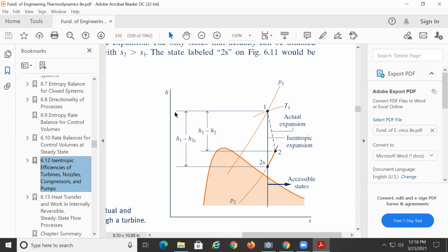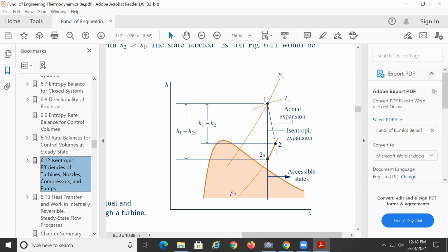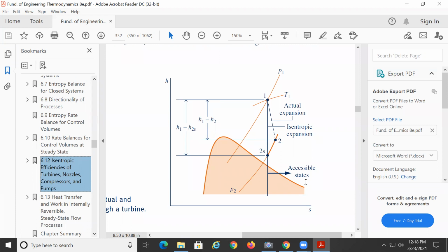It is to transform all that energy into kinetic energy, so you can push on the engine. That's why the air coming out is a lot faster than the air coming in, no? Through the turbine. So basically, what does that mean? You need to go from a high pressure to a lower pressure. All right. So if the system is isentropic, and this is S, what does that mean? That we're going to go between the two lines of pressure that are these ones here, following a straight line down. Okay? So we go from here to here to be isentropic.